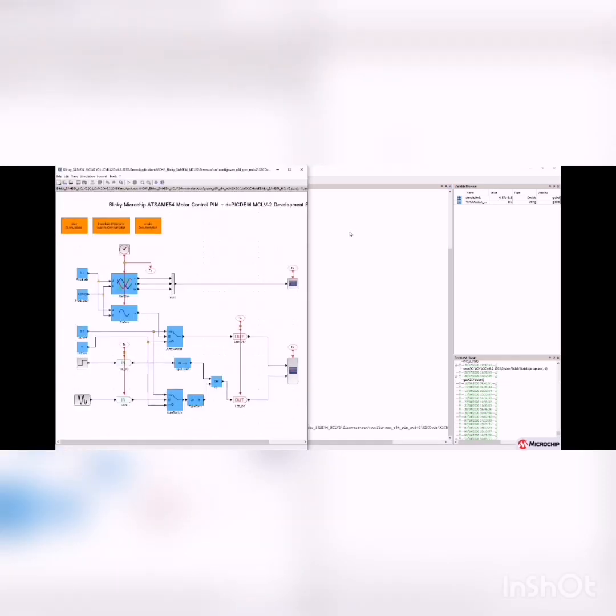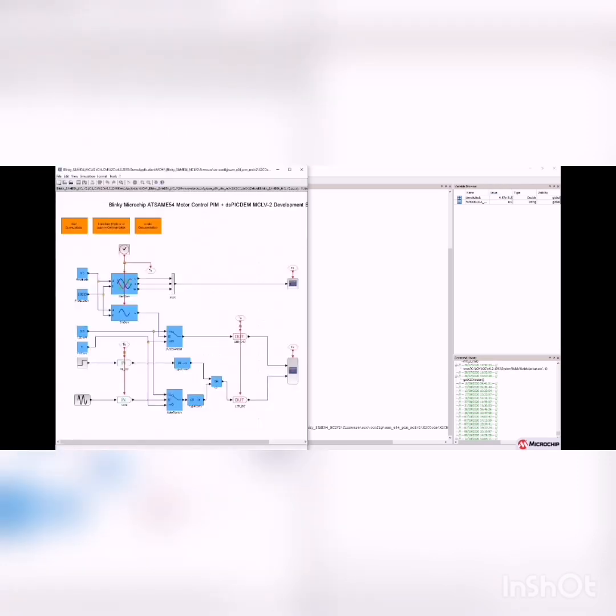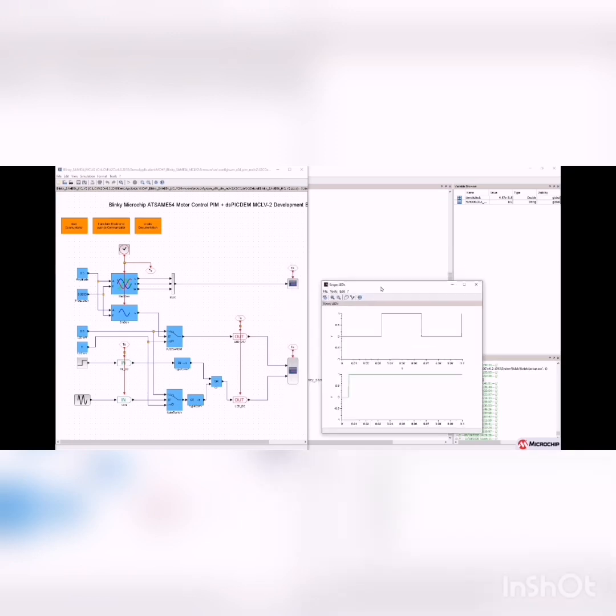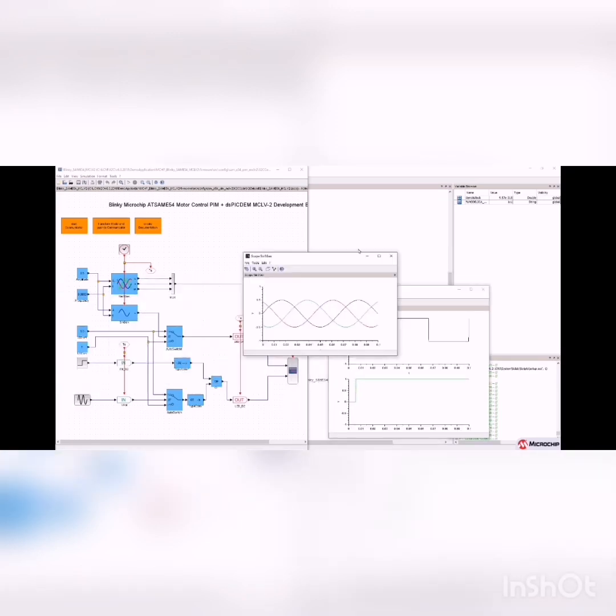If the model also has an init project.sce script, it's highly recommended to execute it at this time. For this, we go back to Scilab. We don't see one, so we don't have to execute it. So now we are ready to simulate our model. We can do this by clicking on this icon here. Simulation starts. Simulation diagrams are coming up.